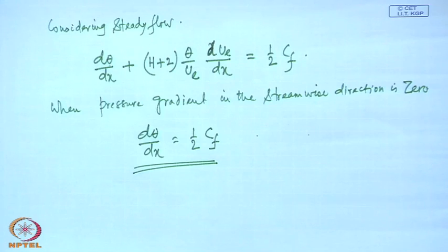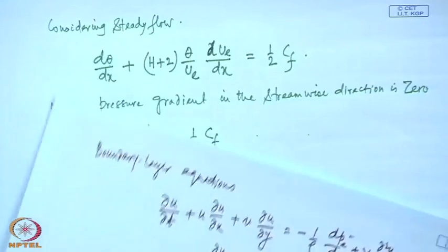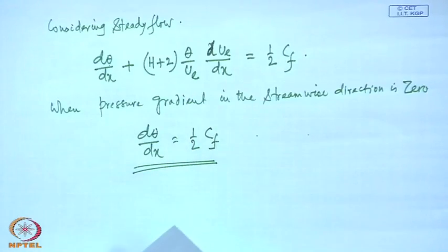So, boundary layer can be solved either by this differential equation approach, where we try to solve these differential equations, or where we try to solve these integral equations. Now, there are solutions available for either format. In the differential form, we can get solutions for some simple flow problems where there is no pressure gradient or where the pressure gradient can be expressed in a very simple form.